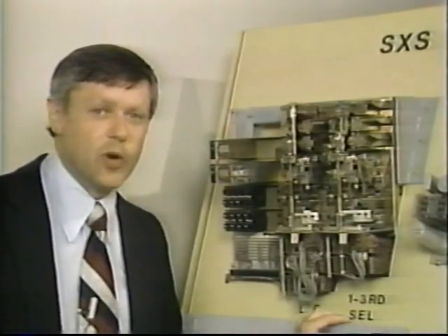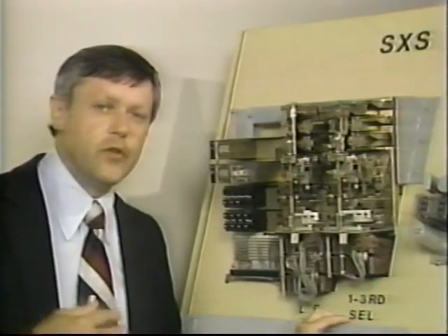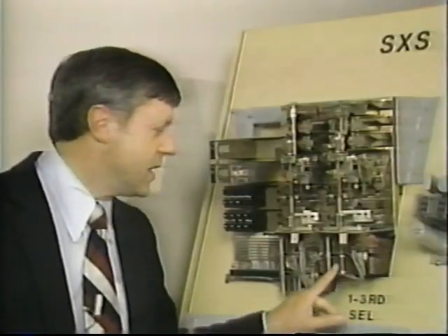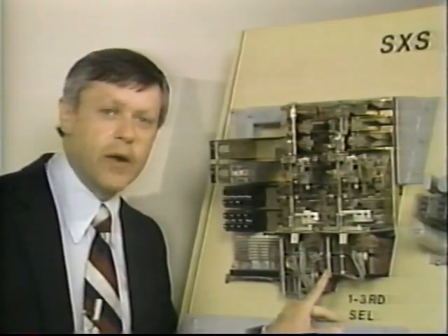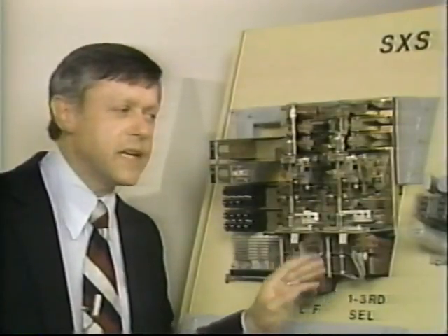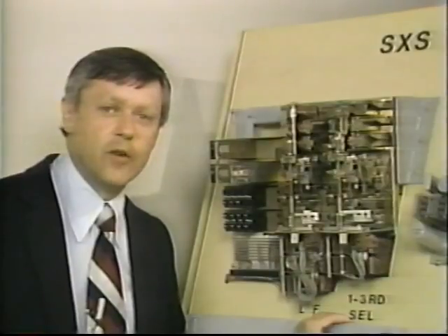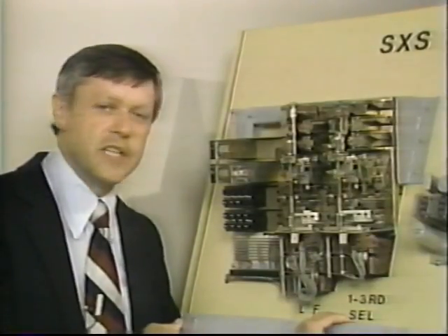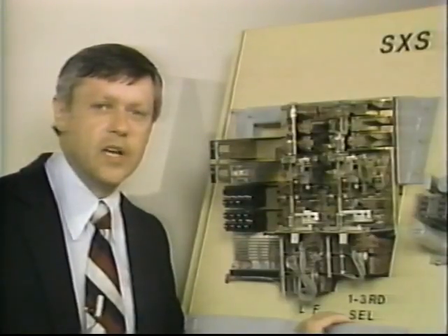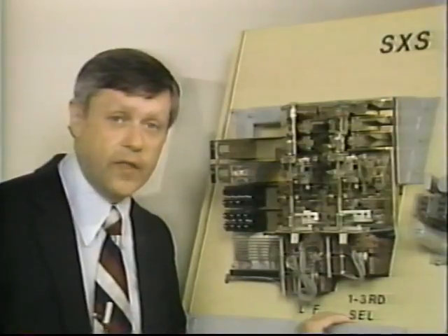Now a couple of last words about step-by-step switching equipment. First thing is, as you noticed when the call was being dialed through, if you watch the tape carefully, this stepper switch was throwing numbers away. It started to step and it restored. That's because we were dialing 675, which was our own telephone exchange. So this stepper said, hey, I'm on 675 and so are the other phones being dialed, so we don't need to connect the first 3 digits, only the last.